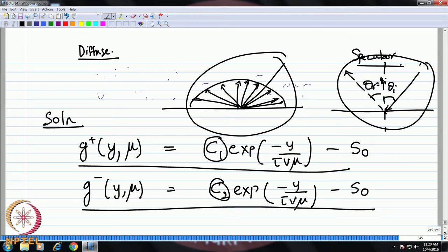Okay. So, when you say F equilibrium is not a function of theta and phi, therefore, whenever your phonon distribution function encounters a diffuse interface, your non-equilibrium distribution F will become equal to F equilibrium because it is uniformly scattered, whereas in the case of specular it is not so.